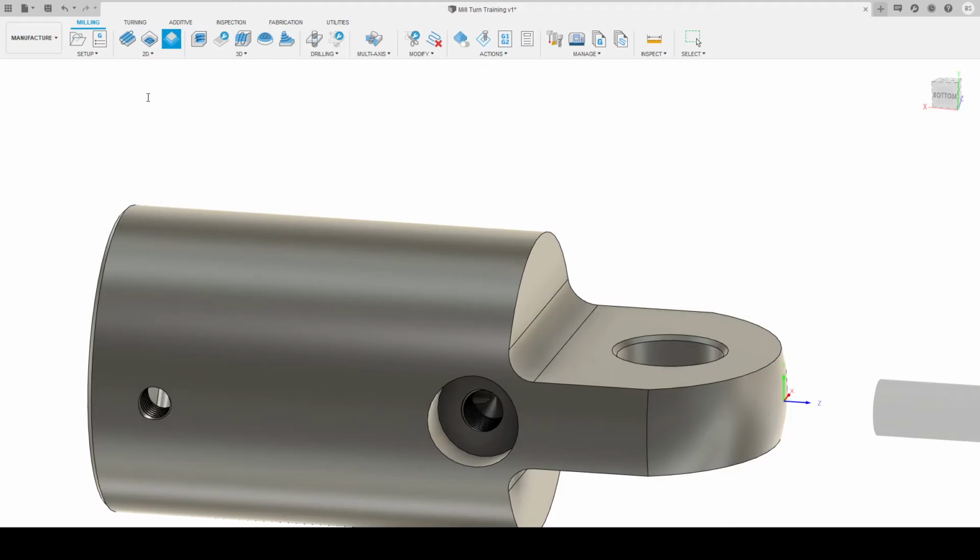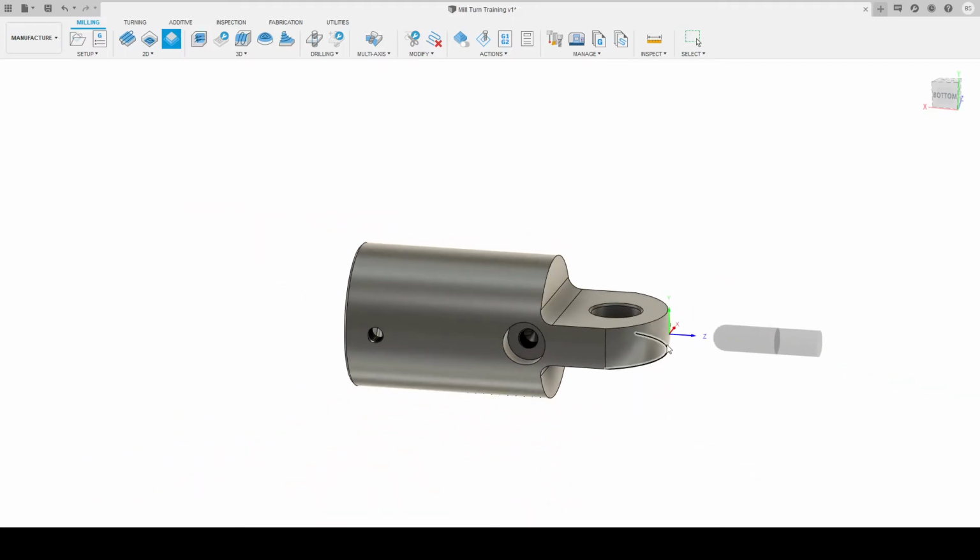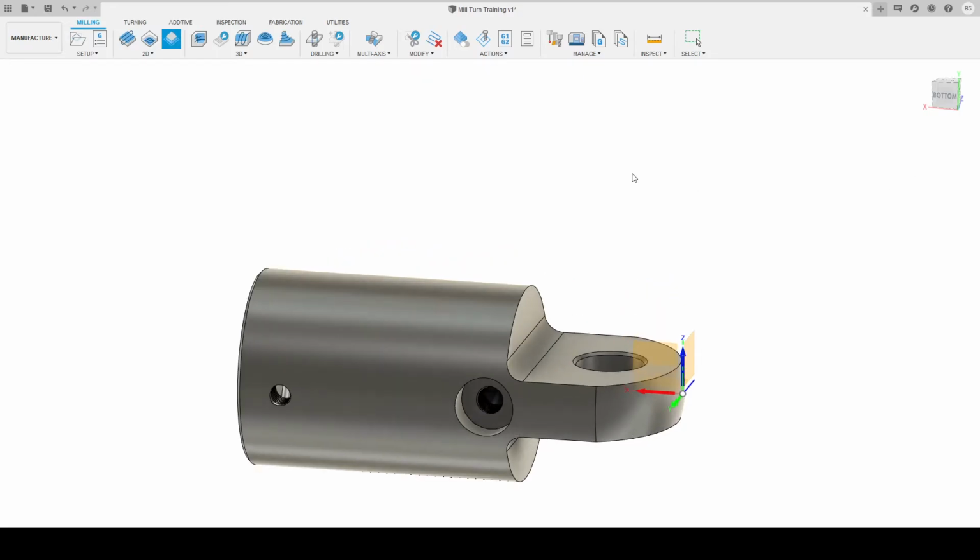Everything else we've been through plenty of times now. We've got a unique number for a unique tool. So we've got 1, 2, 3, and 4. Very good. Select that. So our tool's facing the wrong way. We'll jump into our geometry tab. We will go into tool orientation. We will select that face to get our tool orientated in the correct position. And then the contour we want to select is actually this one.